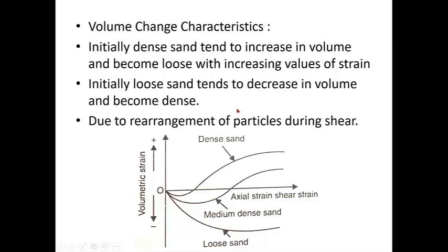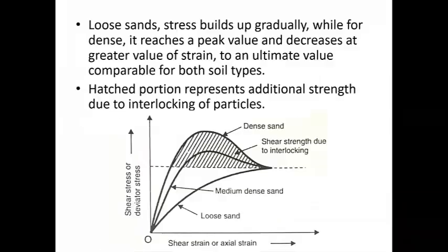Now, if you look at over consolidated clay and normally consolidated clay, which will be in a more dense packing, normally consolidated or over consolidated? Over consolidated will be more dense, isn't it? Yes, why? Because it has already experienced such high pressure in its past, and the particles may have come closer together, so they have better attraction between them. So it will be packed better, of course, right? So it has already undergone some consolidation, and the volume has already decreased.